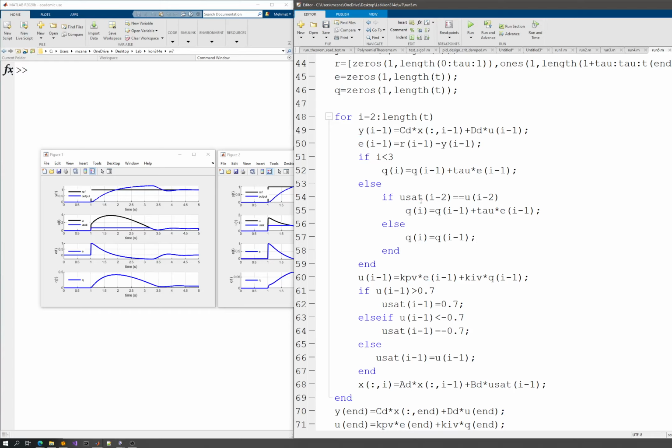So I'm checking for the saturation and the raw data here. If they are the same, then I'm in the linear region, which means that I have no saturation, so I should just use my default integrator. But if a different value in the saturation and in the raw data exists, this means basically that I have to switch off my integrator. Switching off means that my input is E here, so giving E 0 will take care of this part, so this will vanish, and I will have the previous value as a constant here. Hope that this will work.